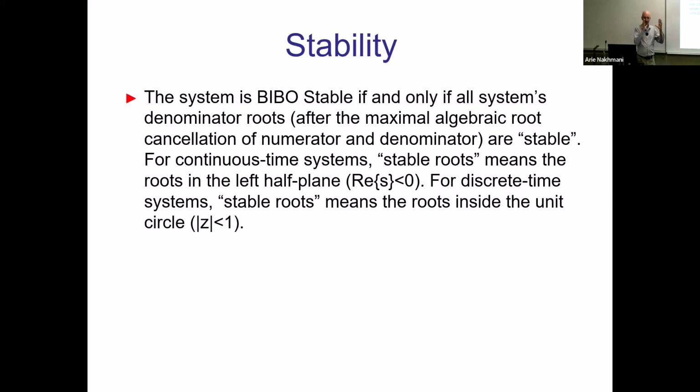So again, zero initial conditions, a particular input which is bounded, so not going to infinity, bounded with minimum and maximum. And the output must be bounded if it is BIBO stable. If it is not BIBO stable, it will diverge for particular inputs, or for all inputs. Sometimes for all inputs, sometimes for some inputs, right? So this is not BIBO stable.